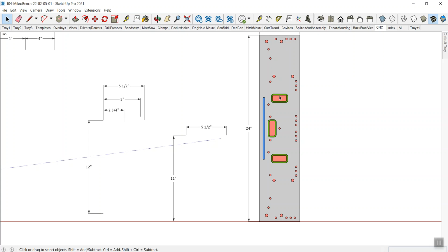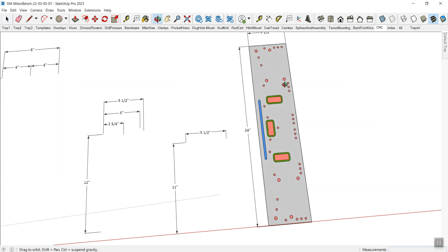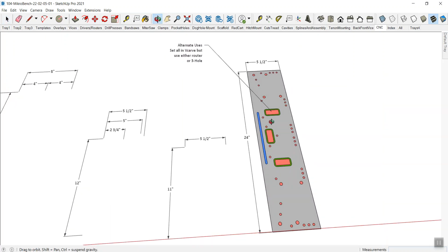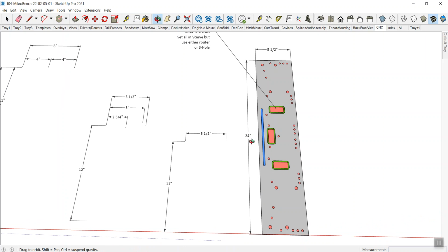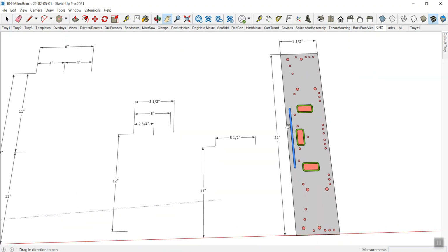The green typically tells me, and this is just a consistent thing I've used throughout, I want to go about 1/4 of an inch, maybe a little deeper at times. I'll kind of remember that. The blue tells me I want to go almost all the way through. So if it's a 1/2 inch template, then I want to go just a little bit shy of 1/2 inch deep. If it's a 3/4 inch thick template, then I want to go to almost 3/4. So anyhow, it doesn't make any difference what angle I'm at or anything else.